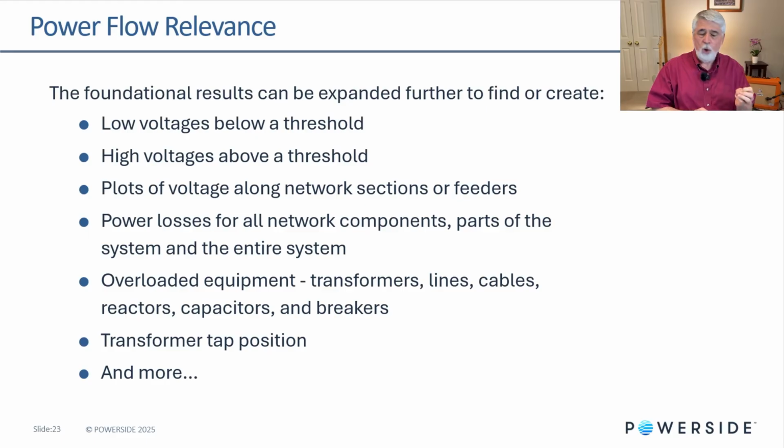Yes, if we have the current flowing through our electrical components, we can calculate I squared R losses. Overload of equipment, transformers, lines, cables, etc. Transformer tap positions if you're simulating load tap changing transformers, and there's even a number more that are the standard reports.